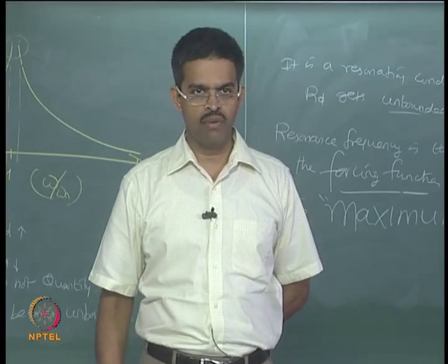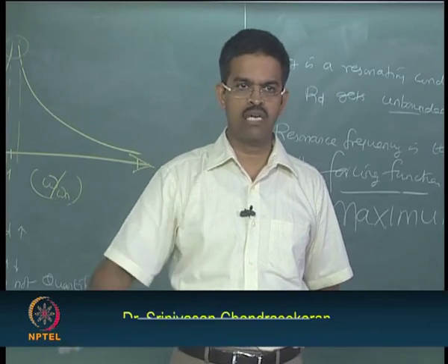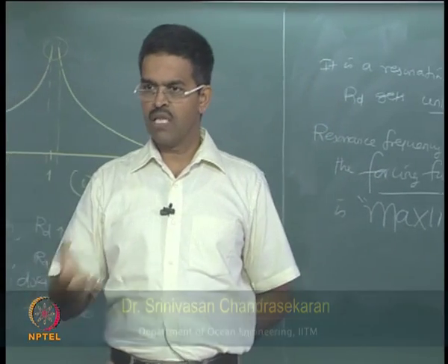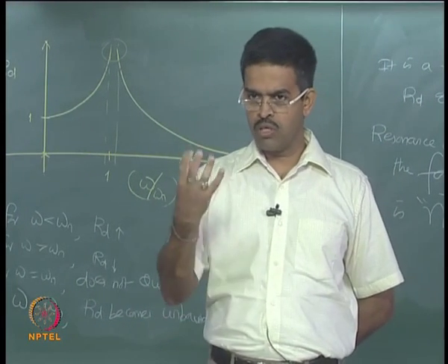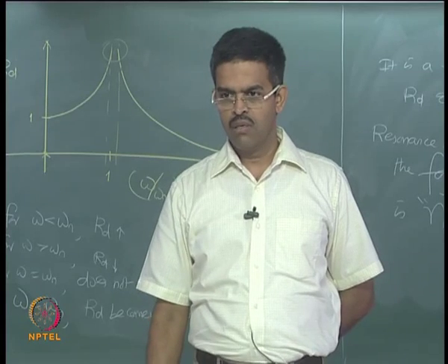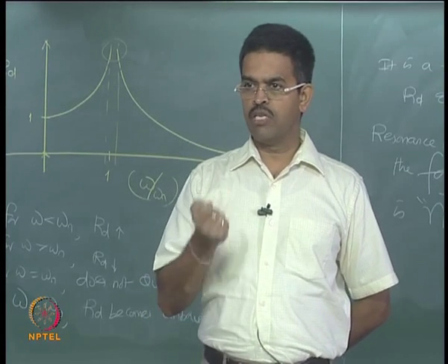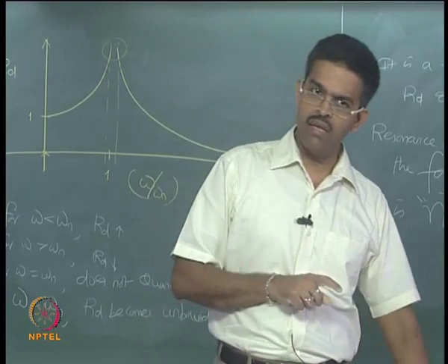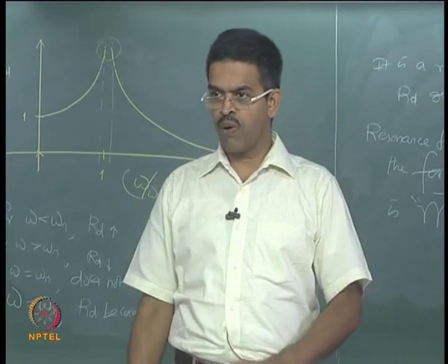Function is not important for me, function is drilling or production, I understand that, but I am putting this platform in different water depths, making the platform either rest on the floor or we hold it down by mooring or tethers, etc., or introducing articulations. So I am changing the form behavior, so that K is also becoming a function of response as well as time.